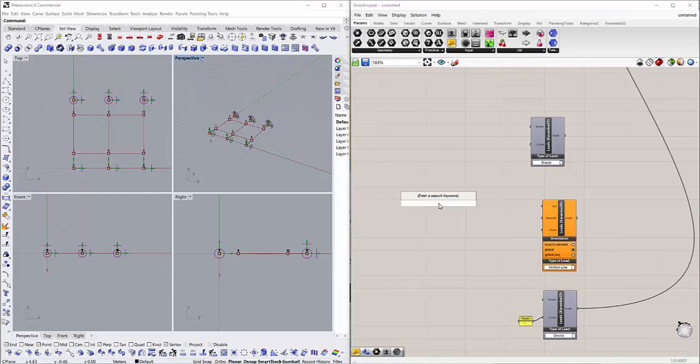And now the next part is I need to create a Z vector and connect it here, and then enter a negative value as my wind load will be acting in the negative. So my wind load is assuming 0.36.